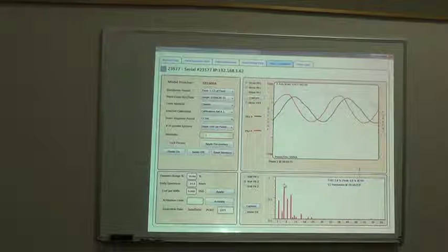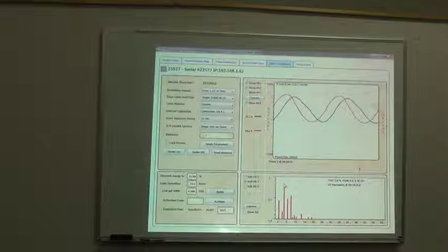What the SP1000 does, basically it calculates what its own effect is, and in the average, it will reduce your harmonics because it's acting like an LC filter. Okay? Basically, every time you have inductance and a capacitance, you're affecting the system. And because there is a low-pass filter, and the harmonics are naturally high frequencies, what happens when you put a low-pass filter on a high-pass signal? You attenuate it, okay?